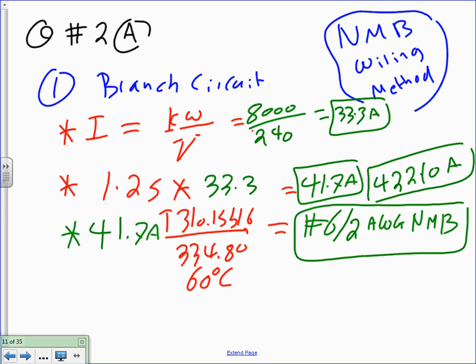What do you say that 422 is for there? That's the 41.7. 422 will tell you that it's a continuous load and you have to size the overcurrent protection device too. You're going to see how we size the overcurrent protection device in a second. So number 6 is 55. You guys are good? Okay. Can I go to this next? The size of the overcurrent protection device?